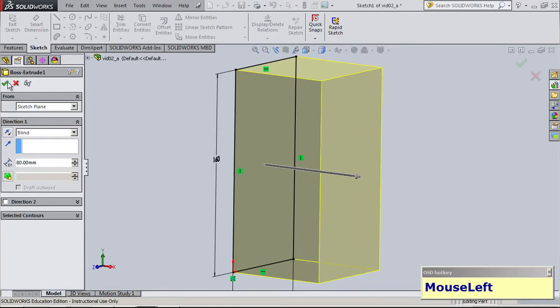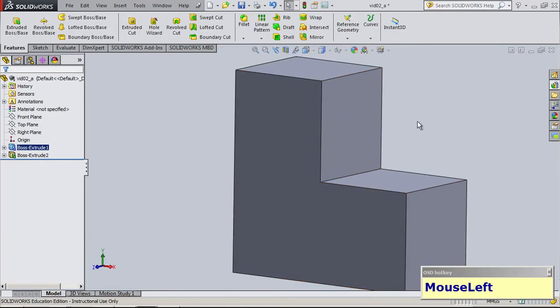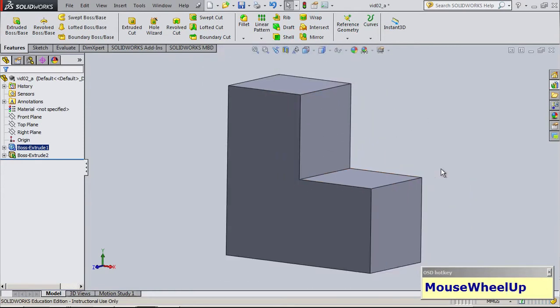And then if I say okay, you'll notice that everything is automatically moved because this sketch was starting from this particular plane. What has actually happened is the reference has moved, and then the face has automatically moved there as well. Right. So this is the first way to create our particular view. So we were basically extruding along the X direction.